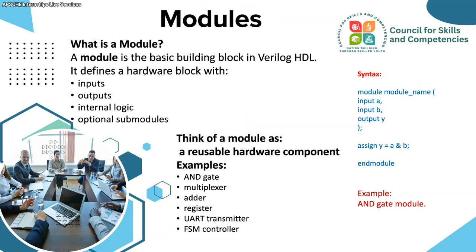Now we will try to understand what a module is. It is like a stone, like a brick. It is a basic building block. A module is a basic building block in Verilog HDL. So what does the module convey? It is going to tell what the inputs are, what the outputs are, what the internal logics are, and optionally submodules.